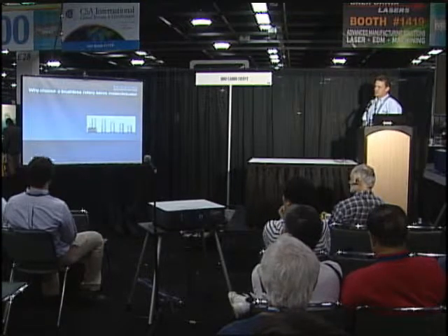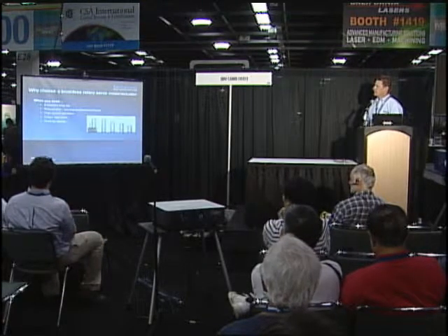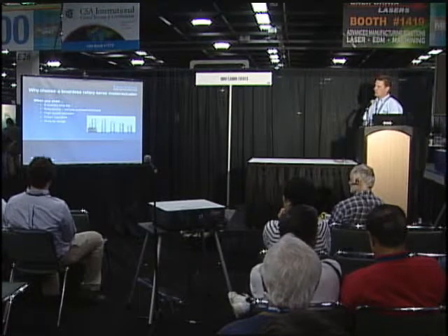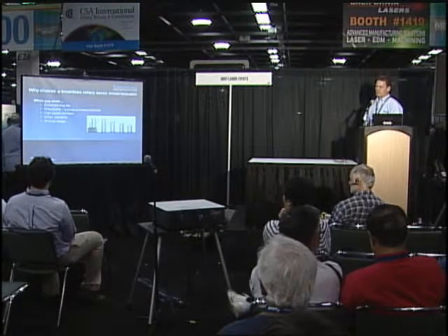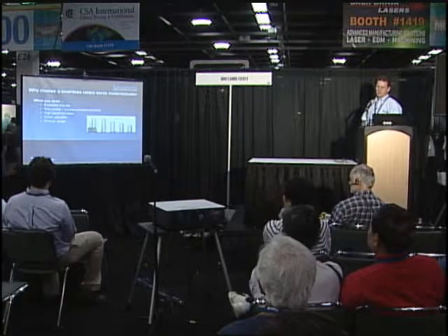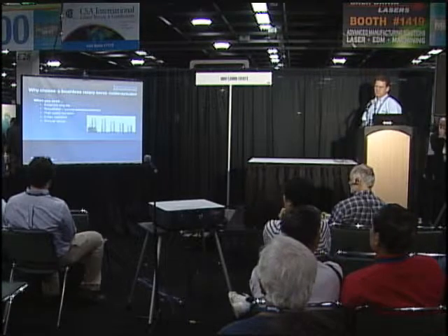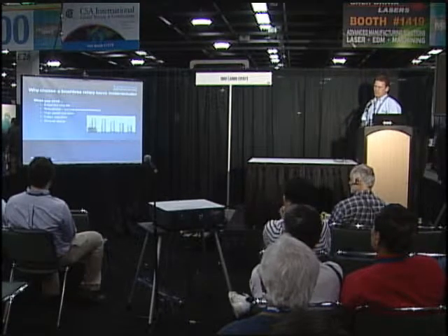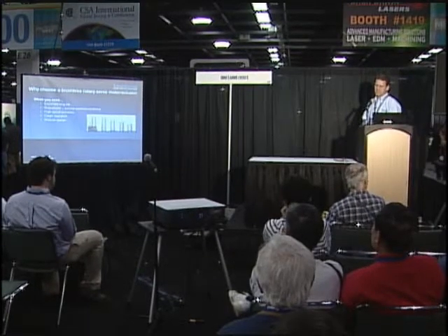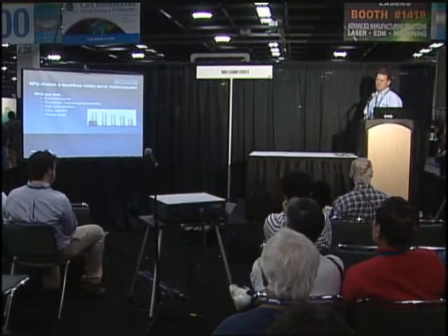In the brushless rotary, you want long life, obviously, if you're considering those. Robustness, they tend to be a bit more rugged. High speed is definitely an advantage with brushless motors. You can overdrive a brushless motor, say a 12-volt motor. You can run those sometimes with 36 volts to achieve 40, 50,000 RPM.